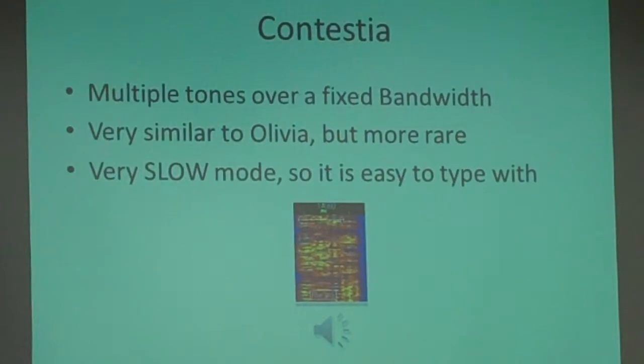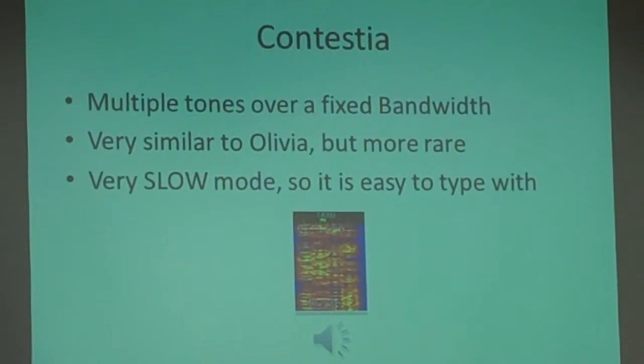I tried to get a good example of it, but unfortunately it doesn't transfer well when you do a screen capture. What you get looks like mirrored echoes off the waterfall. You'll see about 16 hertz in the case of PSK31 on either side, or maybe 8 hertz, and then another 8 hertz and another 8 hertz. They end up taking up 125 hertz of bandwidth, even though they're running PSK31, because they've got that processing up too high. It's very similar to overmodulation.